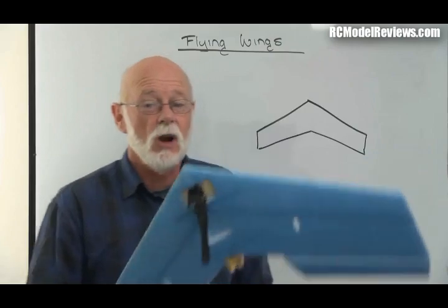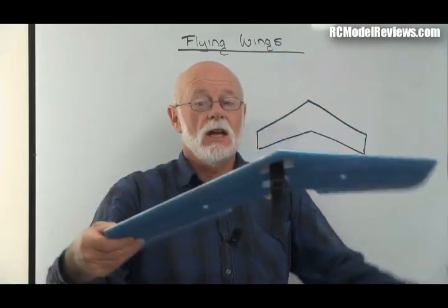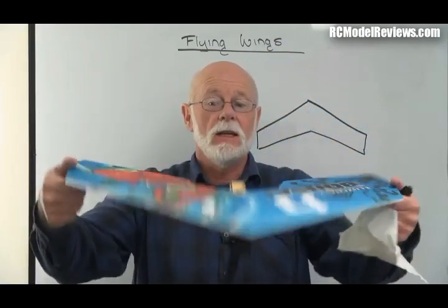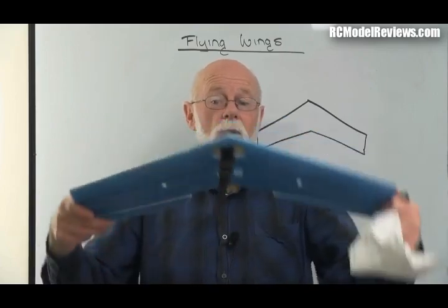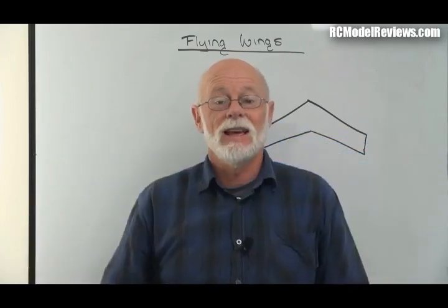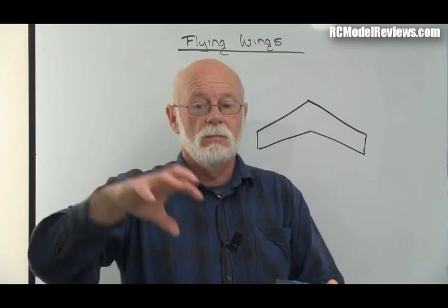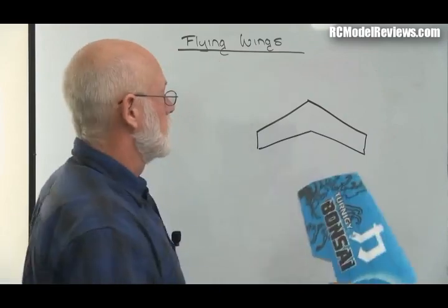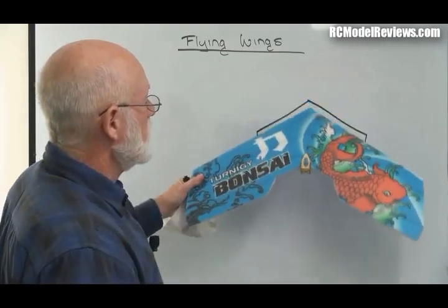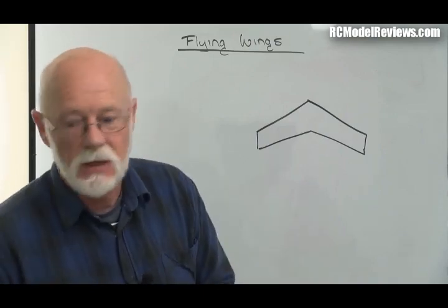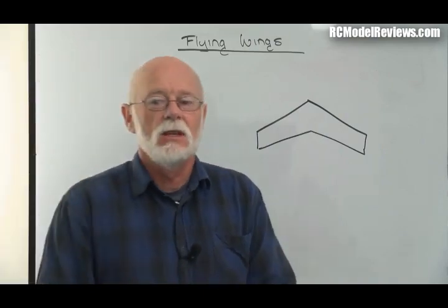In fact, you get a lot of Dutch roll sometimes with swept wings. And that Dutch roll is this, woo, what we're talking about. It's Dutch roll. And it's a real problem, which is why a lot of aircraft have anhedral to cancel that out. And they also need big vertical stabilizers to help there as well. So anyway, back to what I was talking about. How are we going to stop the effect of this yaw roll coupling and this wibble wobble?